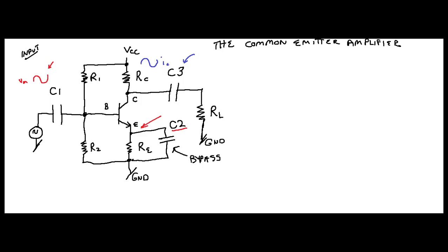If you have a voltage coming in here, it just passes right through that capacitor. You see your base is going to have this same type of curve. It's going to go through your emitter. This is like a diode, so it's going to give it a 0.7 volt drop, a reduction in voltage, assuming it's a silicon transistor, which it is. So then your voltage here at your emitter is going to look the same, right?